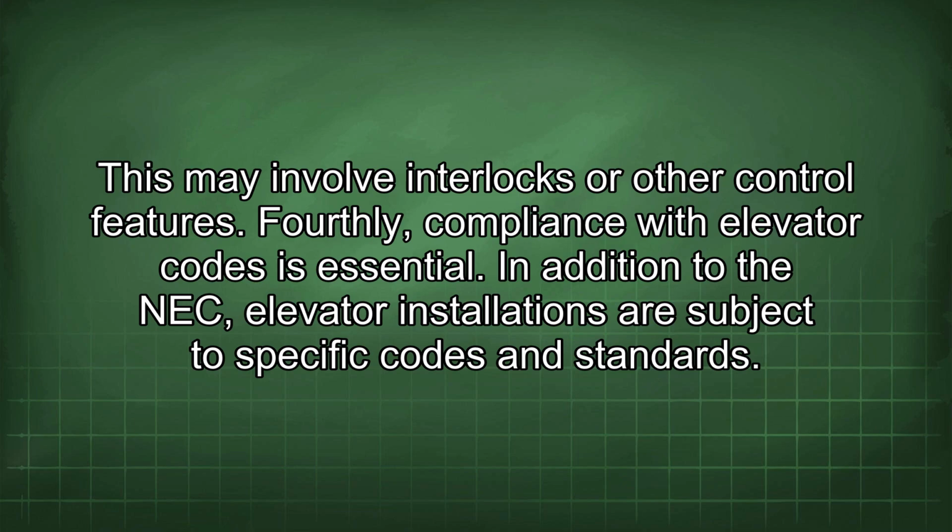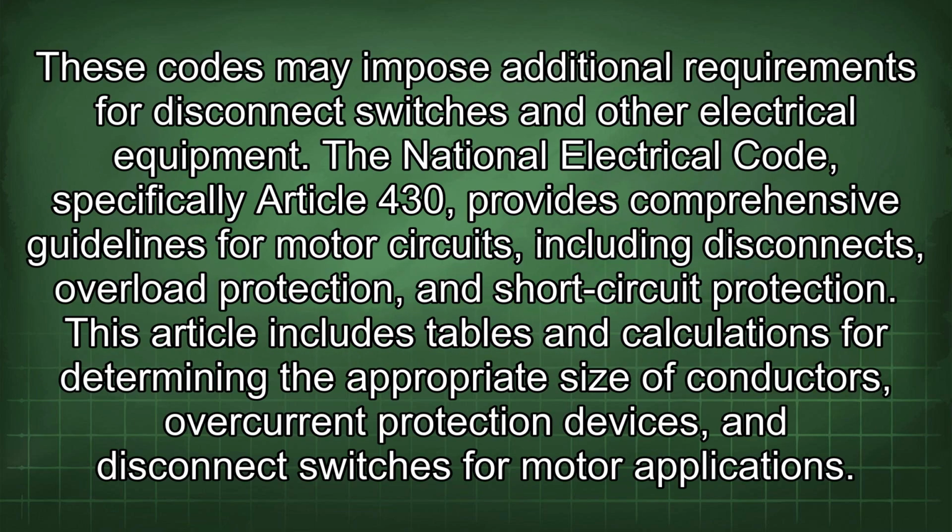Fourthly, compliance with elevator codes is essential. In addition to the NEC, elevator installations are subject to specific codes and standards. These codes may impose additional requirements for disconnect switches and other electrical equipment. The National Electrical Code, specifically Article 430, provides comprehensive guidelines for motor circuits, including disconnects, overload protection, and short-circuit protection. This article includes tables and calculations for determining the appropriate size of conductors, overcurrent protection devices, and disconnect switches for motor applications.